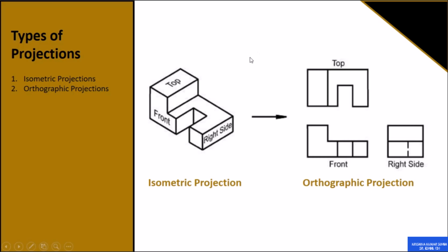Here we have the angle of 120 degrees. If we draw an imaginary line then we have a 30-degree angle here. So this is known as isometric projection. The second thing is that all the lengths are different. The lengths in orthographic projection are slightly higher than isometric projection, because isometric lengths are represented according to the isometric scale. We will discuss them in specialized sections.